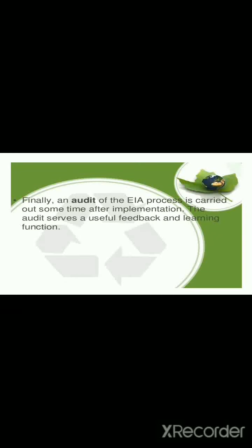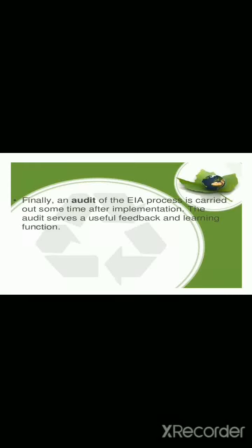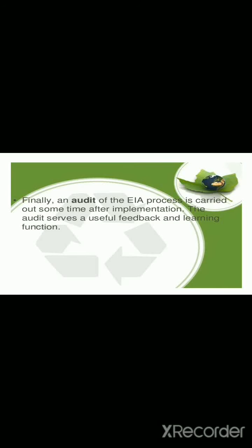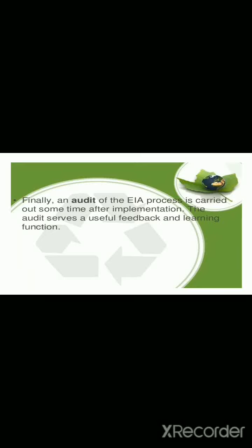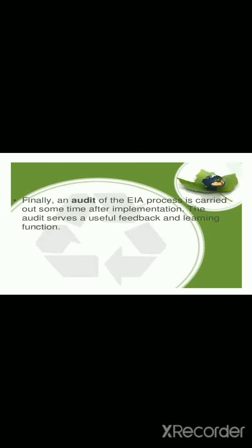For a description of the existing environment, precise data relevant to the site is required. That is, describing intended uses, quality, and the physical, biological, social, and economic conditions. The description must include other existing or proposed developments. The use of maps, graphs, and drawings is very important for a better understanding of the situation. And key data gaps and uncertainties must be identified here.